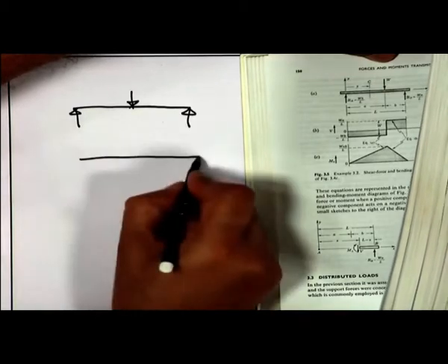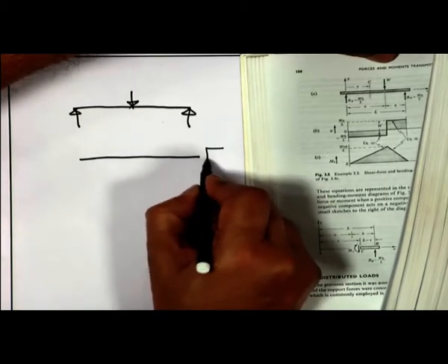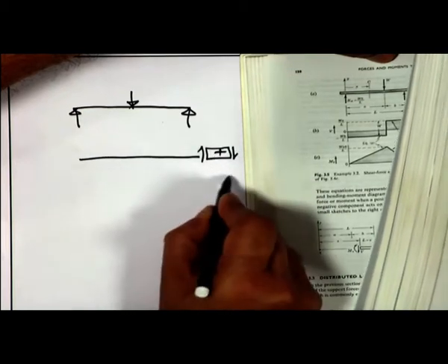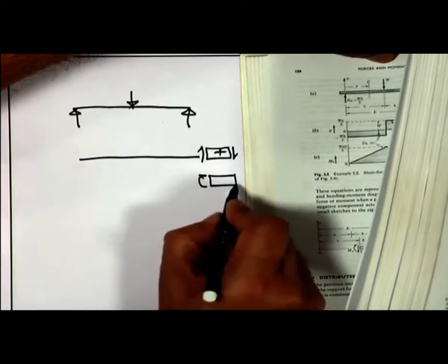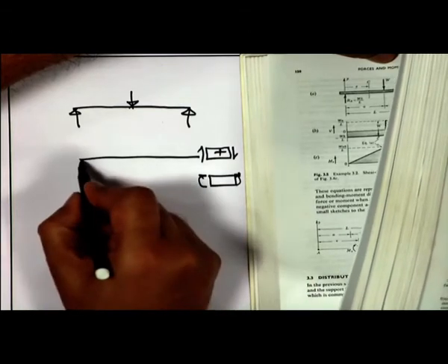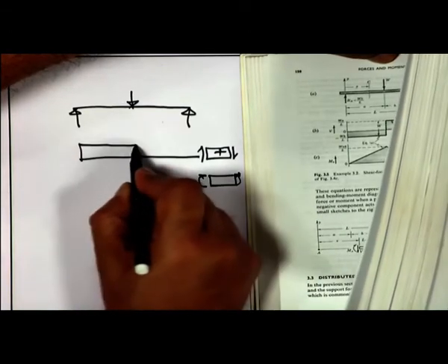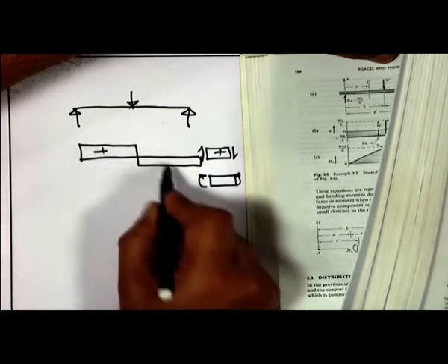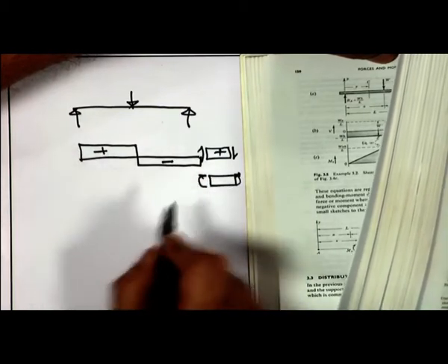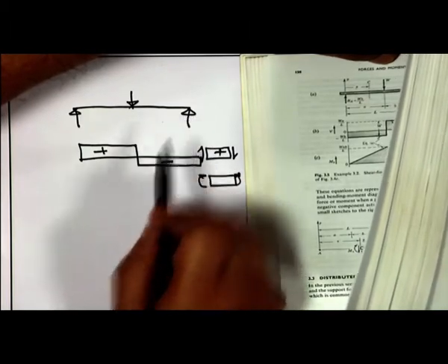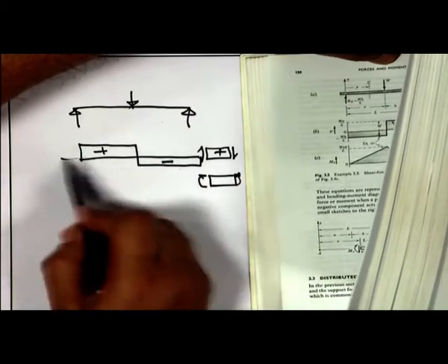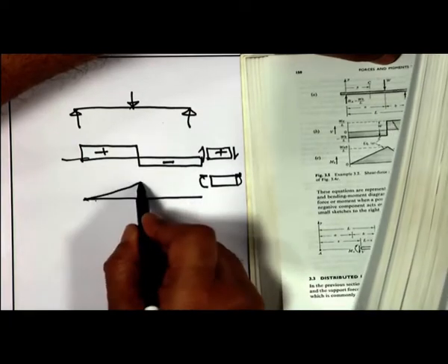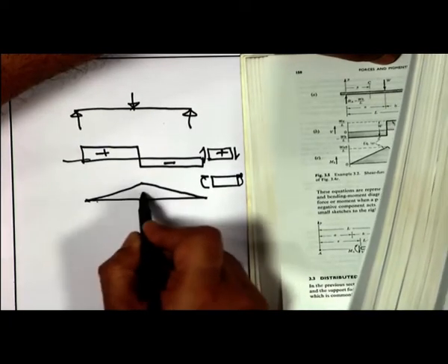My shear force diagram, according to my sign convention, has left up, right down positive for the shear, and for the bending moment this. So, the same shear force diagram will be drawn like this, where left up is positive and right down is negative. According to this, this is negative shear, and this is the middle line, and for the bending moment I have the same thing, there is no issue with that.